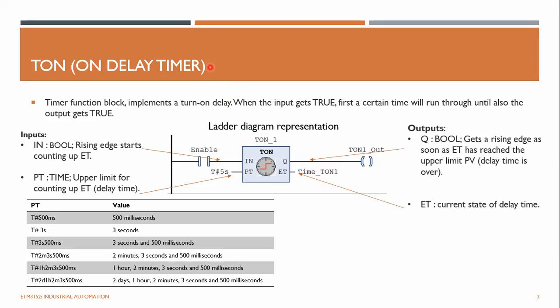It counts the number of clock pulses, and based on the clock frequency, it can determine the amount of time. Similar to microcontrollers, in PLC we have a quite handy and simple way of using timers. They are just a graphical representation as function blocks. In text programming we use a delay function, but here in PLC programming, in a ladder diagram, we just use timer blocks.